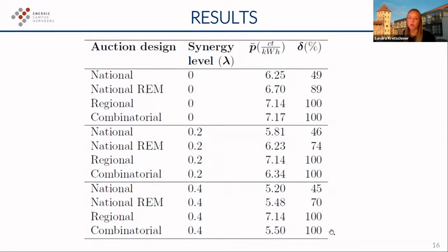And what's also important to note is that this remuneration, so this 5.5 cents per kilowatt hour here, does not even include the long run cost savings that would result from lower redispatch and network investment requirements when the regional target capacities from the system optimal case are implemented. So the cost for which, I said this before, were 1.5 billion a year in 2017, for example. So even though the feed-in premium might be the same, the resulting savings from the combinatorial case would make this case actually a lot cheaper in the long run.